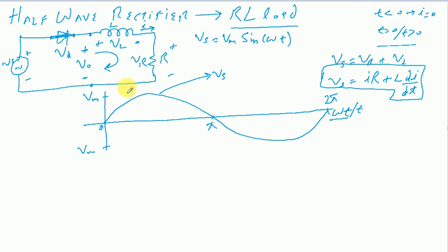of similar nature. Previously, as I had mentioned, we'll have a current that will be completely in phase with this voltage waveform. That is not going to be the case here due to this inductive load, because the inductor has this basic property that it does not allow an instantaneous change in the value of current. So current cannot instantaneously rise through an inductor. In the same way, current cannot instantaneously fall to 0 through an inductor as well.